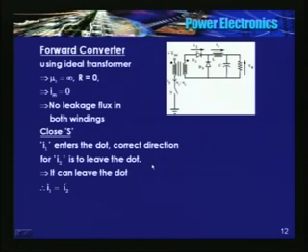that current has to be continuous. See, this inductor current is continuous because DF provides a path. When I close the switch, I2 starts flowing, that is nothing but IL, DF was off. So this is the path. When I open the switch, D2 turns off, so this current can flow through this diode.